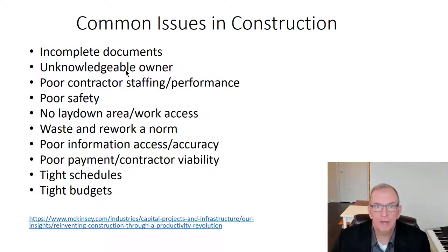Poor contractor staffing performance, that would include all your subcontractors, right? That ties into time, cost, and quality. All of those cause issues when somebody doesn't do something when they're supposed to, or they do it but don't do it to the specifications and you have to redo it. Construction safety is a big concern. We talked about the moral and ethical side of things. We want to make sure that we're operating in as safe a way as possible and that we're doing our due diligence. Site logistics, making sure that the site is best set up to manage the project and organize it in an effective way.